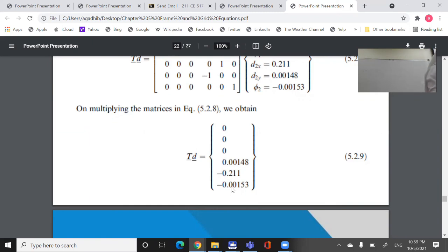Yeah, elongation, exactly. Local, everything is local now. Now how do you go to the shear, and we'll finish. How do you go to the shear and the moment? If you want to draw shear and bending moment diagram for member number 1, you take those displacement, which is in local, you multiply it by what? K, which is the local.